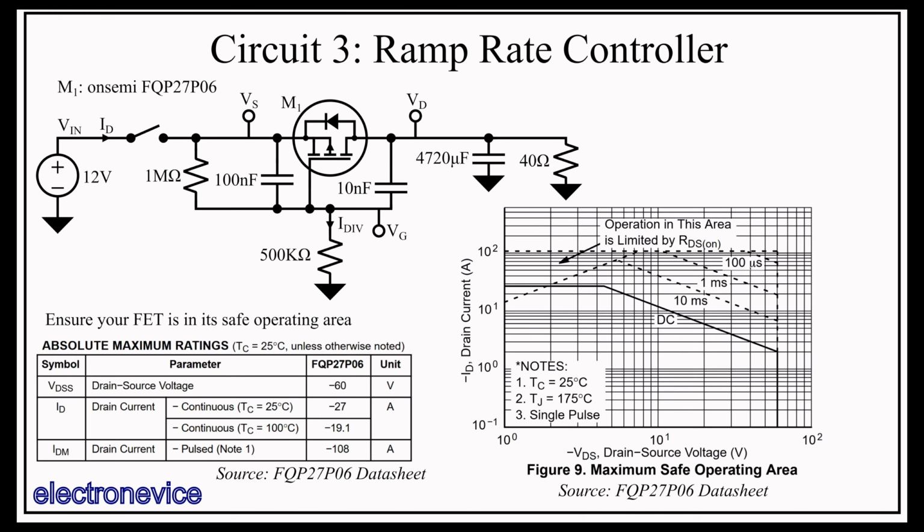This one assumes a case temperature of 25 C and a maximum junction temperature of 175 C, and that for the durations other than DC, it lasts for a single pulse with a long period of time between pulses, so that the FET is relatively cold before another pulse happens. Note that a case temperature of 25 C means that you need really good heat sinking to keep the case at 25 C if your room temperature is something like 20 C, as 5 C is not a very big temperature difference between a FET burning a bunch of power and the room's air.